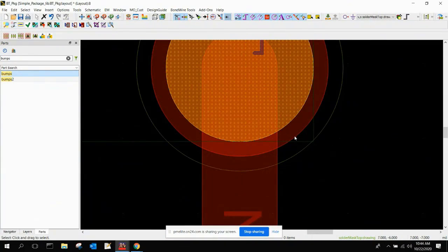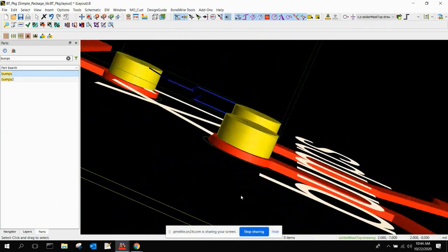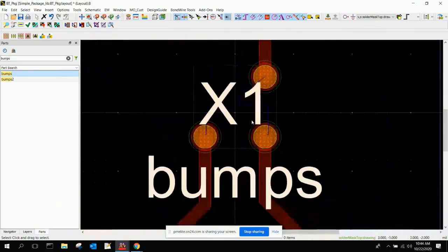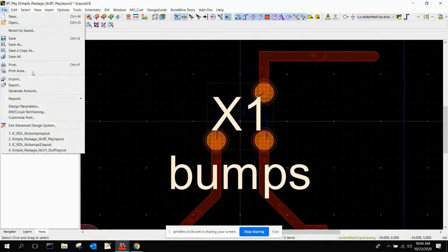Now it expands out. It draws the layer in the technology that I'm putting it in, and then it blows out even further, and it puts the solder mask opening on there automatically. So these layers are generated by the thing that I'm instantiating in the other technology. And the cool thing about it is, if I was to take this and export, if I wanted to make manufacturing